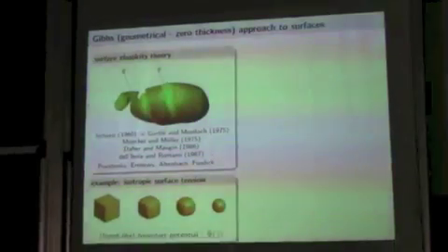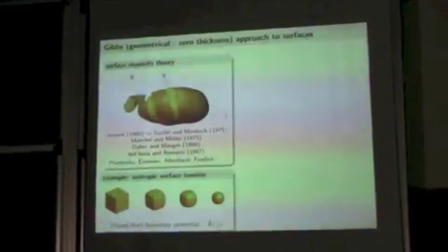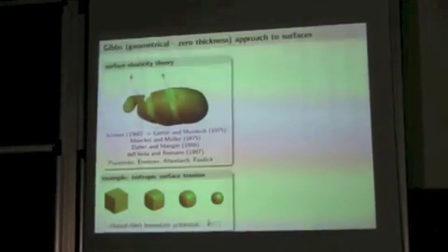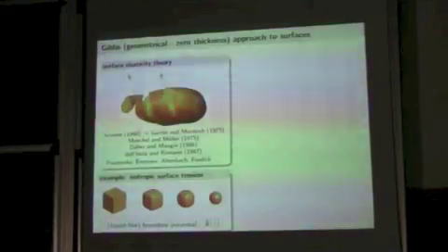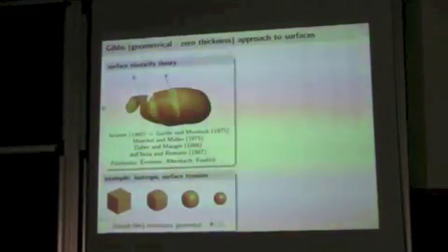Now, if we want to look at an example, this is a very interesting example. You take a cube, you apply a surface tension. Surface tension means constant energy per unit area in the deformed configuration. So now your structure wants to reduce its energy. For a given volume, you know that the sphere has the minimum surface. So the cube transforms into a sphere. And that's exactly the reason that a droplet of water is generally spherical. So this is an interesting benchmark, and you can actually calculate your surface tension by this. We have done this. It's a very cool thing.